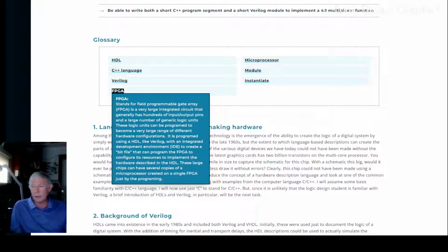This integrated development environment creates a bit file from our hardware description language code, which we can write in several different hardware description languages, but the one that we teach in this department is Verilog. The others are named VHDL, SystemC, SystemVerilog, and some others. But currently, Verilog is probably still the most used one, although SystemC and SystemVerilog are moving in to sort of take over eventually.